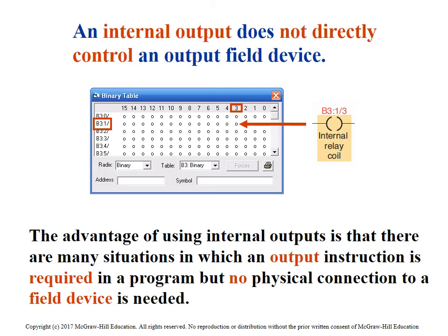Internal relays, essentially what they're saying here is that we quite often develop our PLC programs using what we call internal bits. That way we're not turning on outputs and flashing lights and all these different things. When we're developing our code, we want to develop everything using internals.